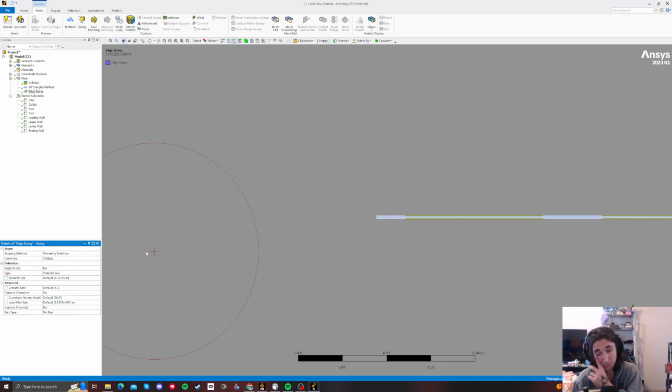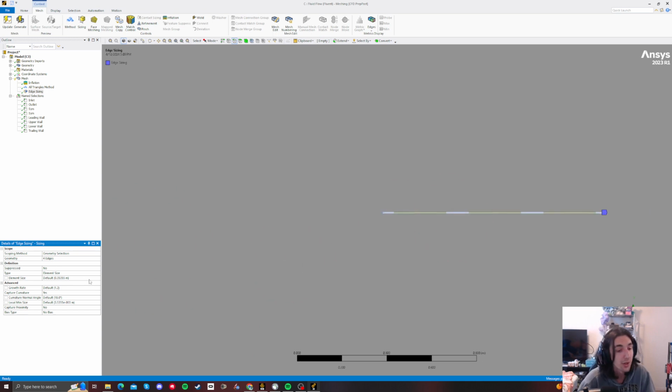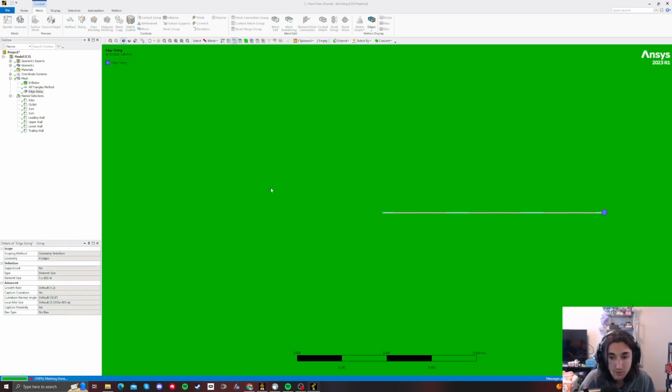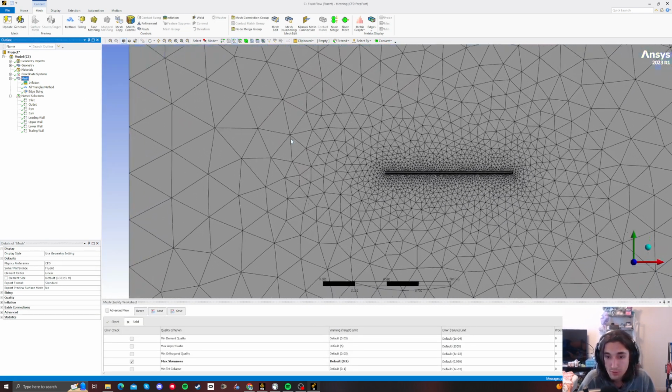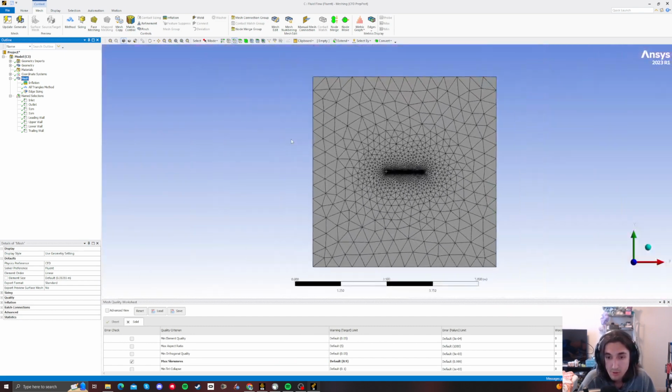So it's going to sort of give you this weird like 3D idea of what you're doing. I don't know why it does that. Okay, so element size we'll do 0.01. I did for my sim 0.001, but I'm just going to try to make this generate a little faster. And then generate. And if we hit mesh, you can see that's a much thinner, nicer looking mesh.